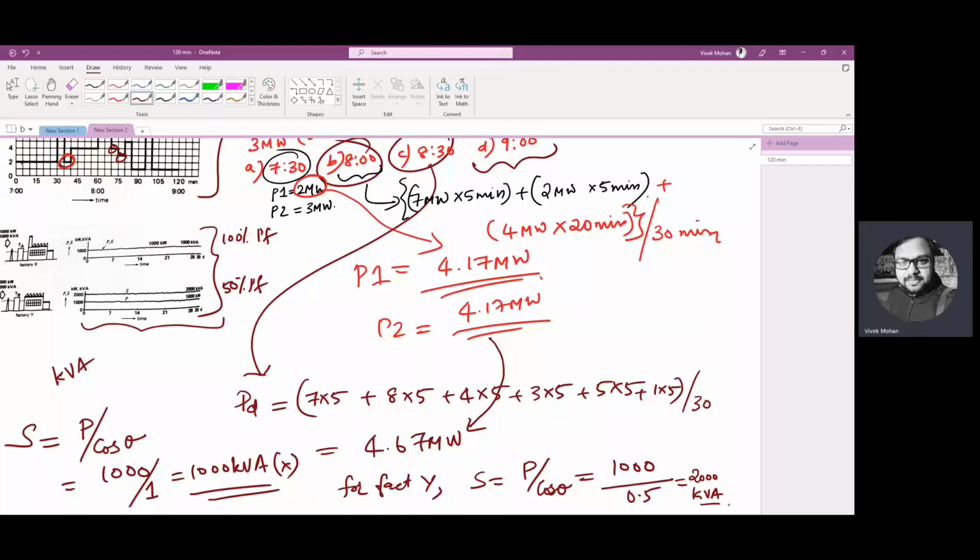Then the transformers, circuit breakers, disconnect switches, and other devices supplying energy to Y must have twice the rating of those supplying X. So in general, the infrastructure cost is more to feed energy to factory Y, as its power factor is half the power factor of factory X. Then the utility company must invest more capital to service factory Y, and consequently it is logical that it should pay more for its energy, even though it consumes the same amount.